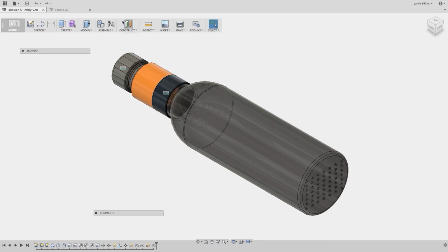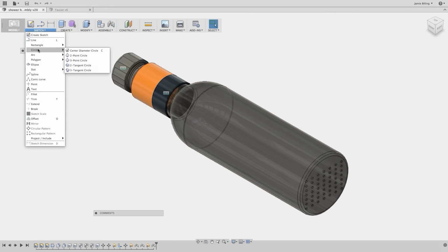In the toolbar, we can find all the tools that are available to us. I'm in the modelling environment at the moment, so if I select Sketch, I can draw lines, rectangles, circles, or arcs. And if there's something that I use a lot, for example, I use two-point rectangle a lot, I can click to add it to the bar.